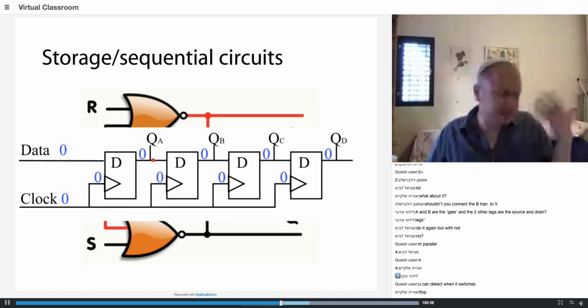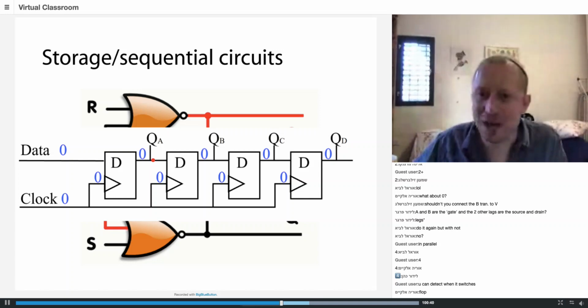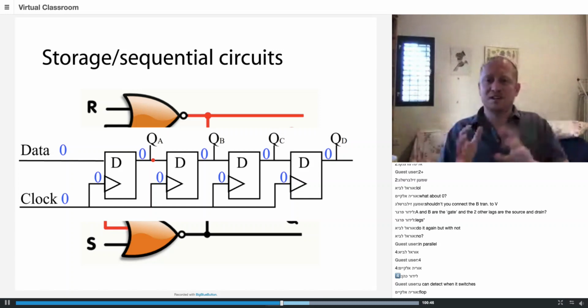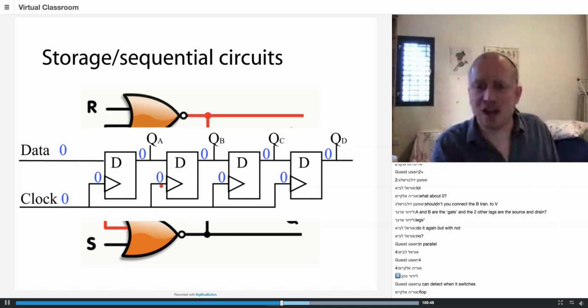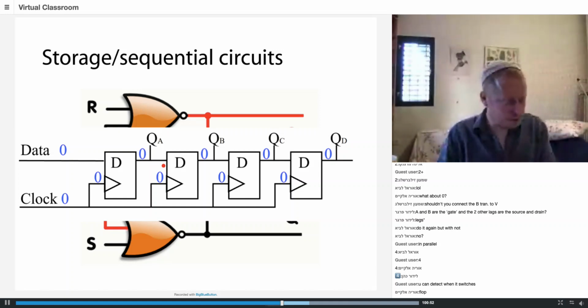And you can think, as an attacker, if you bang the drum too quickly, what happens? Then you have what is called a hold time violation. It means that some of the flip-flops haven't finished calculating, and then you have all sorts of crazy stuff going on. We'll talk about this when we get to faults next.